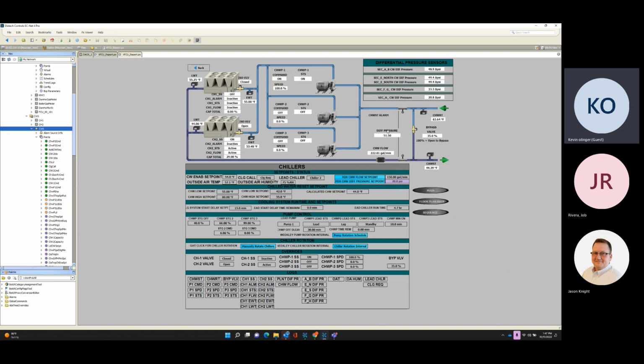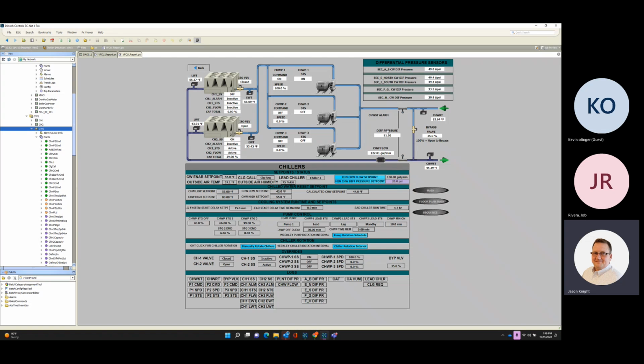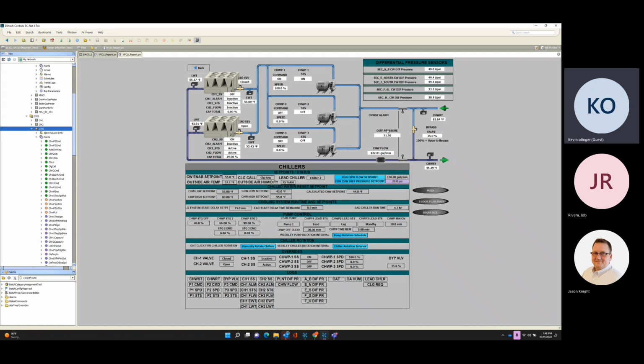Yeah, it'd be interesting to see the relationship with all the three-way valves, because that's typically how you would do some of this tuning, based off of three-way valves out in those zones so that you guarantee minimum flow. And it sounds like we may be butting up against the engineered minimum flow. I should probably look at the valve schedule before I say this, but I'm pretty sure there aren't any three-ways.